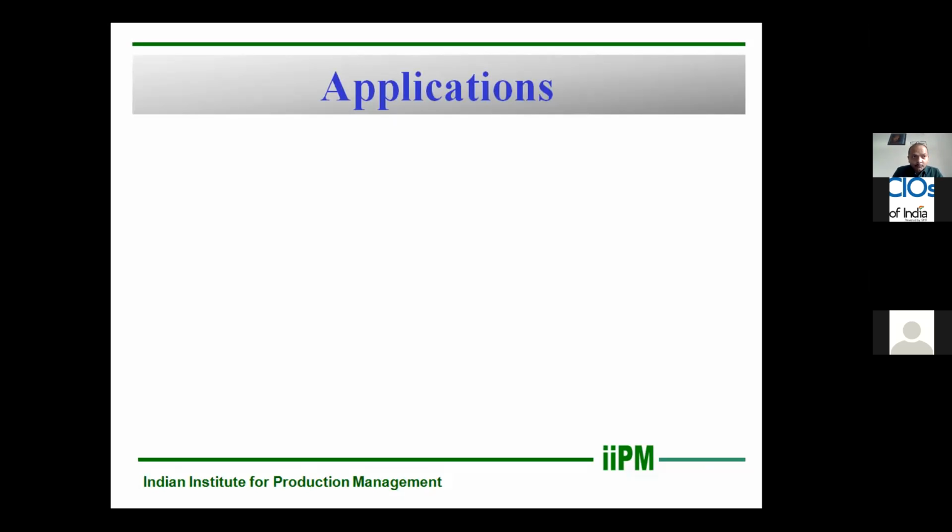To do that, you need to do some kind of condition monitoring of those critical assets. And as Bishwajit just mentioned, vibration is one of the most important parameters to be tracked, because if the machine is running with very high vibrations, it may lead to a failure, and that failure could be catastrophic, or it could be just limited to the equipment not being available. So that's the context with which we need to think through.